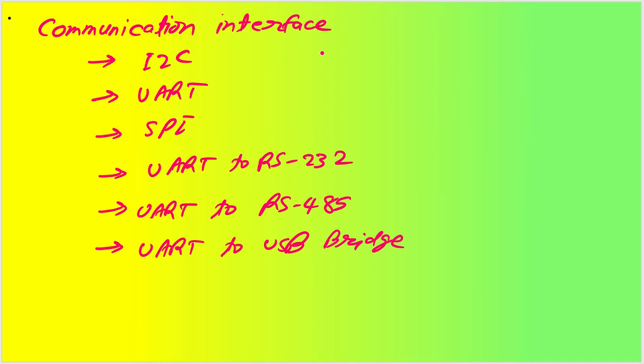Coming back to the communication interface, which is the best part of your board design. If you need I2C communication, almost all the microcontrollers already have I2C pins or I2C capabilities, so you can interface directly through your microcontroller pins. Same case with UART as well as SPI.